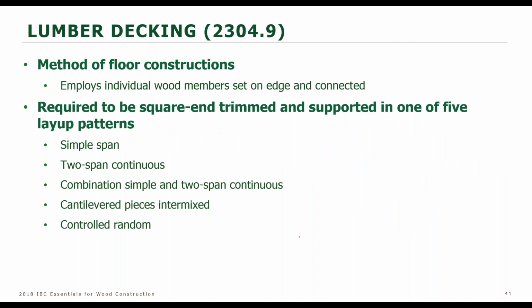Also, you will find some specialized sections that are more prescriptive. This one on lumber decking, 2304.9, gives you prescriptive means to lay out and connect heavy timber decking, and nail laminated timber floors would be found in this section. So this would be helpful in design if you're using large dimension lumber decking in your commercial buildings.